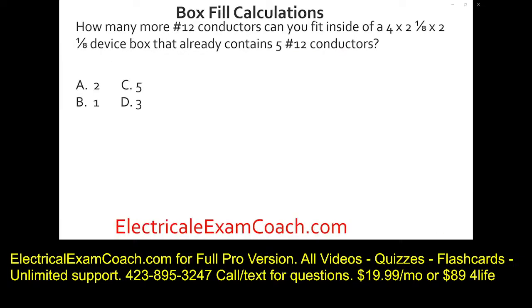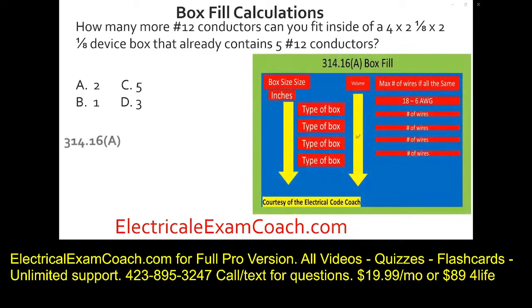How many more number 12 conductors can you fit inside of a 4 by 2 1/8 by 2 1/8 device box that already contains 5 number 12 conductors? For this one, we're going to head back to our table 314.16a. First, let's find out how many wires it can hold originally. It can hold 6. We already have 5, so we take 6 minus 5 equals 1, and we can put 1 more conductor inside of this box.